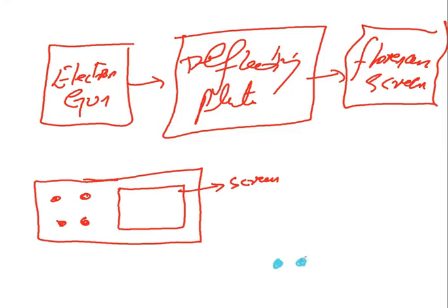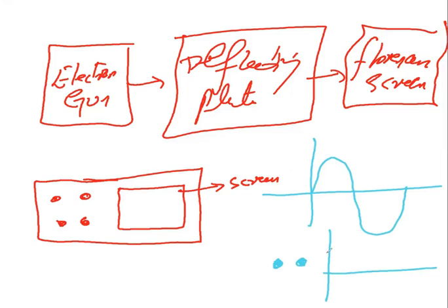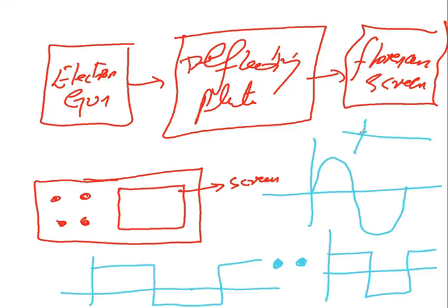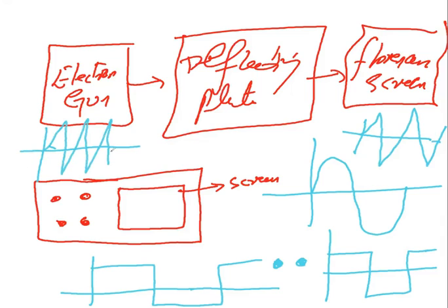The pattern of voltage is sinusoidal. Sinusoidal means like this, a sine graph. And this is the square pattern, the rectangular pattern. This is the triangular pattern. This is the sawtooth pattern. These are the different patterns. And these are the harmonics. If this sinusoidal wave from your home electricity has noise, it means there are some harmonics, other frequencies present inside this wave curve. Later on we will study what these patterns are.